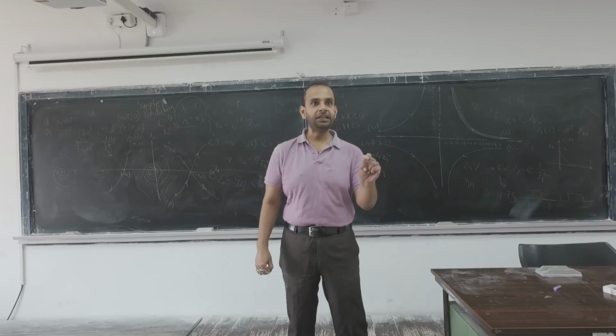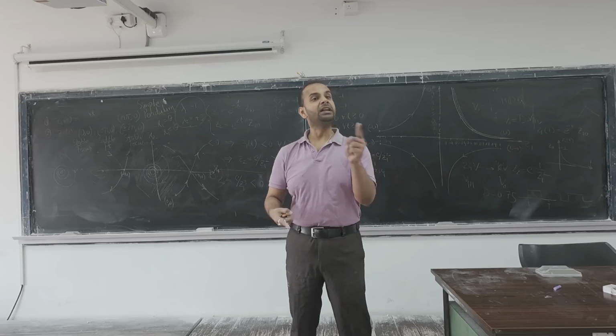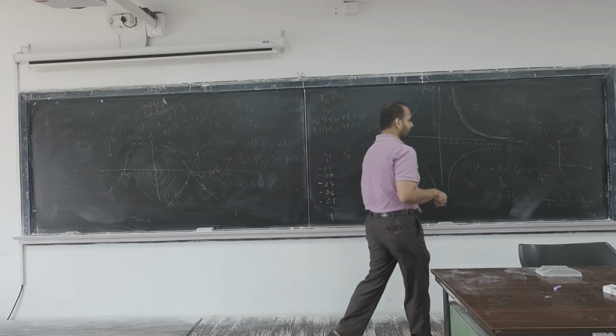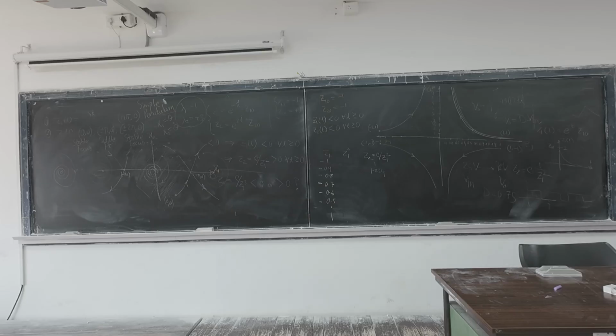Now for the T on, there will be one stable equilibrium point with respect to which the system operates. During T off, there will be another equilibrium point which is also stable. Someone was asking whether we can have a system with two stable equilibrium points. I told him yes, that is possible in some particular cases, but it cannot happen on its own. There has to be an external influence, because if you have two stable equilibrium points, the system cannot autonomously move from one to the other. There has to be a forcing function. Here, the forcing function means the gate control.